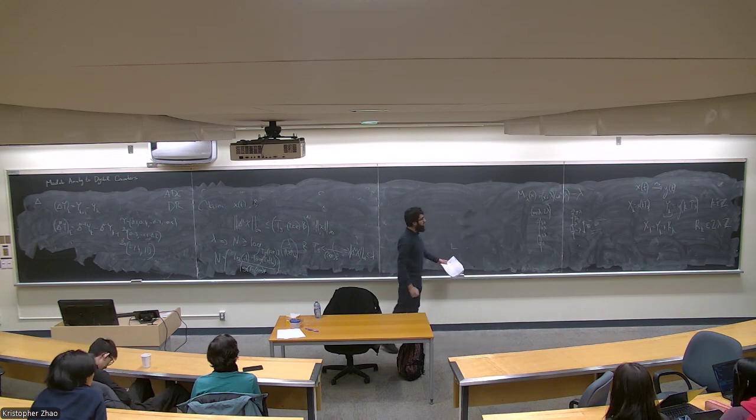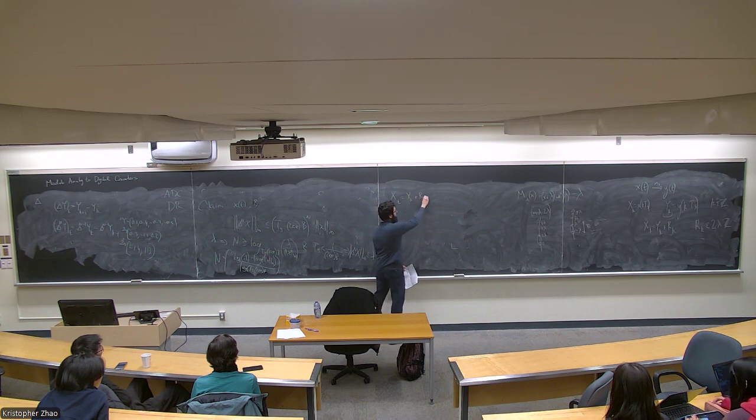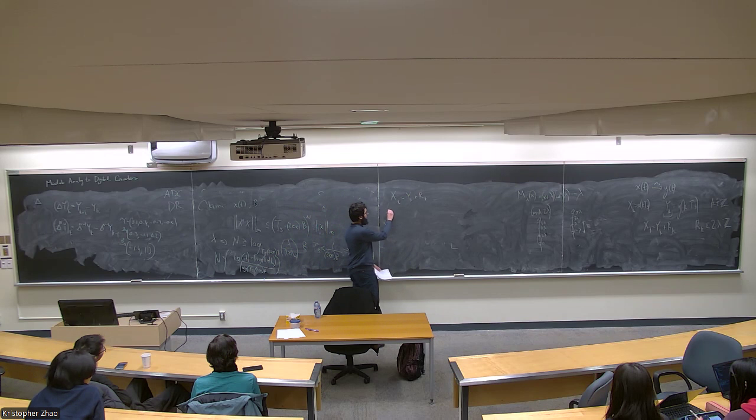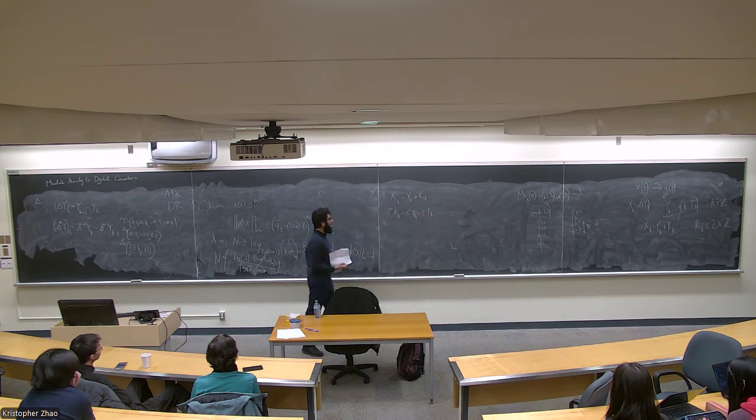So from that decomposition that I had, just to summarize, the samples x are always samples y plus r. If you apply the nth finite difference on both sides, because the nth finite difference is also a linear operation, you'll get that delta n x k equals delta n y k plus delta n r k. And now we can also apply the modulo operation M lambda on both sides, because that's also a linear operation.